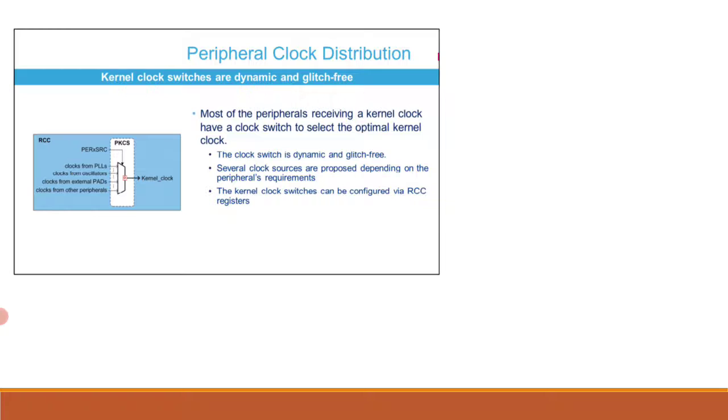Pads, for example, on peripherals using an external PHY, but also for audio as well, in order to use a clock reference from an external device, or other internal peripherals for synchronization between the blocks. The dynamic switching facilitates the transition from one source to another. The RCC registers are also used to configure the kernel clocks for all peripherals.